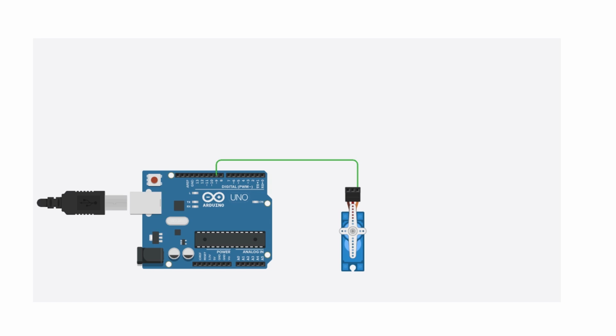But sometimes I don't want to provide the power source to that servo from the Arduino, as it might not be able to provide the current needed, as the Arduino can only put out a limited amount of current. In which case, I might want to power it from an external power source.